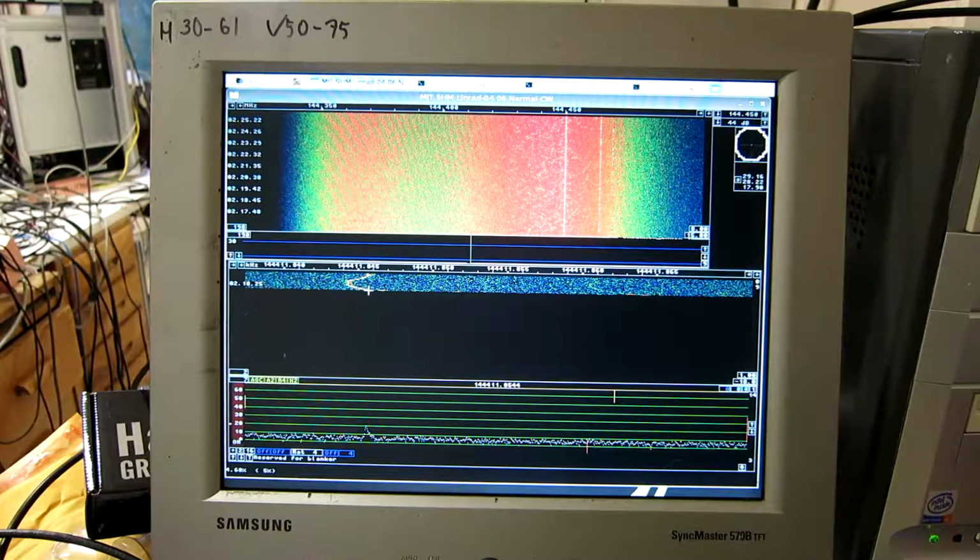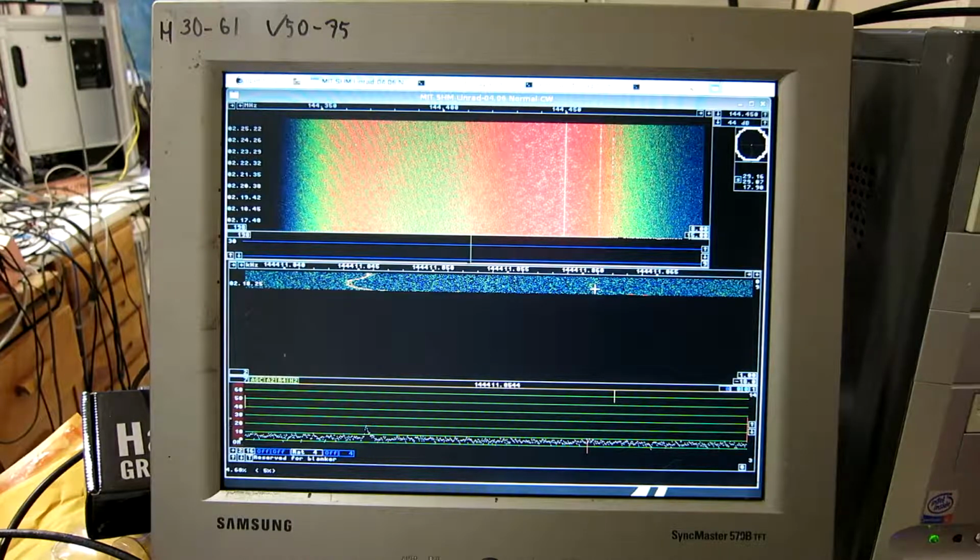The beacon SK4MPI is here, and the signal from the signal generator, which is now 10 decibels below the noise floor in 1 Hz bandwidth, is the same level as I showed before, and we can see it, but in the main waterfall we see nothing, because the second FFT is disabled and the bandwidth of the first FFT is too large to allow anything to be seen in the waterfall at the low levels that we are looking at now.